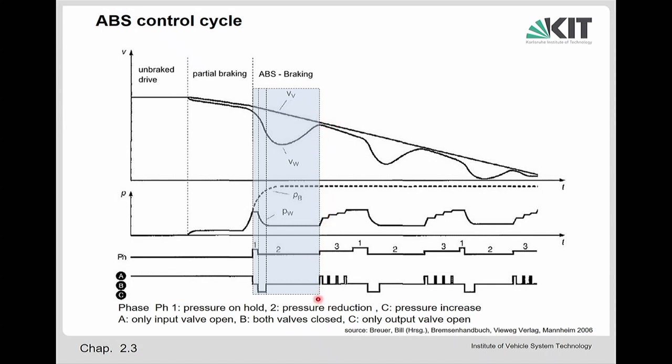And so here, with some short boosts, the inlet valve is opened, and by every short opening, the brake pressure in the wheel brake is increased, which will increase the slip, will increase the force which can be transmitted to the road. But then we come again into that situation which we have here also, and now everything starts from the beginning.